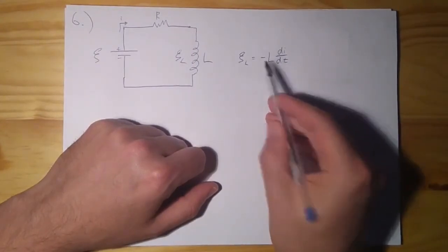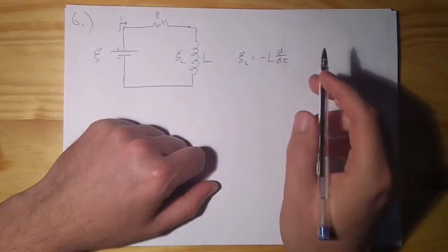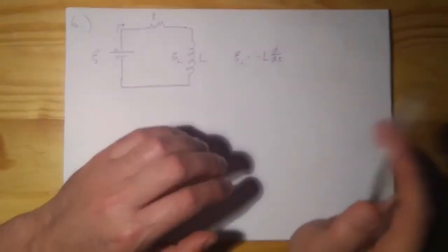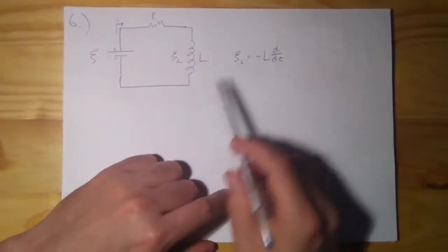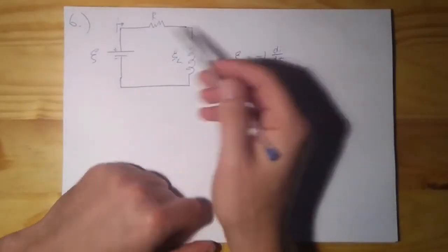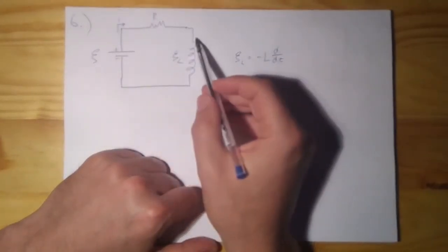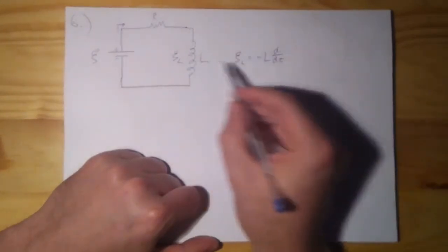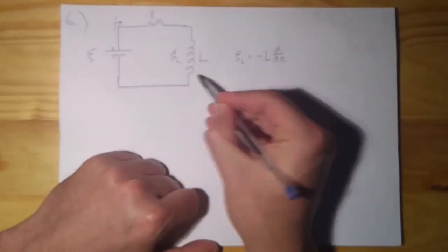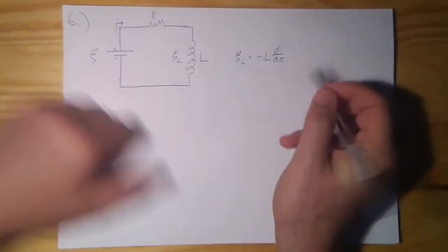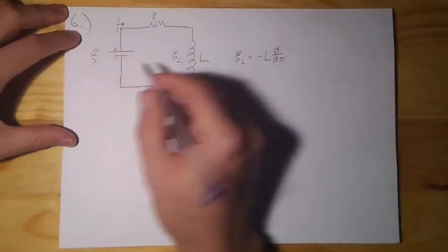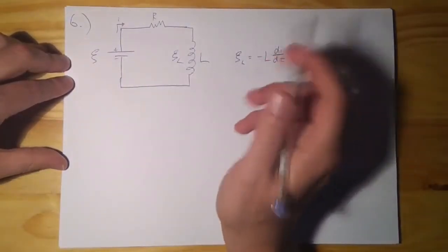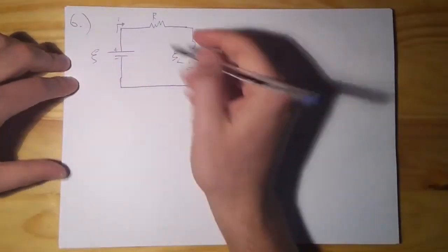That is called Lenz's law, which you can use to determine in an electric generator in which direction the current is going to be generated. Okay, but anyway, all you need to know for this problem is that if the current is increasing or decreasing, in this case increasing as the switch is closed, the current through the inductor changes, and the induced EMF in the direction of the current is just minus L di/dt. It's an EMF that's induced due to the magnetic flux changing, due to the strength of the current in the coils changing. Okay, good.